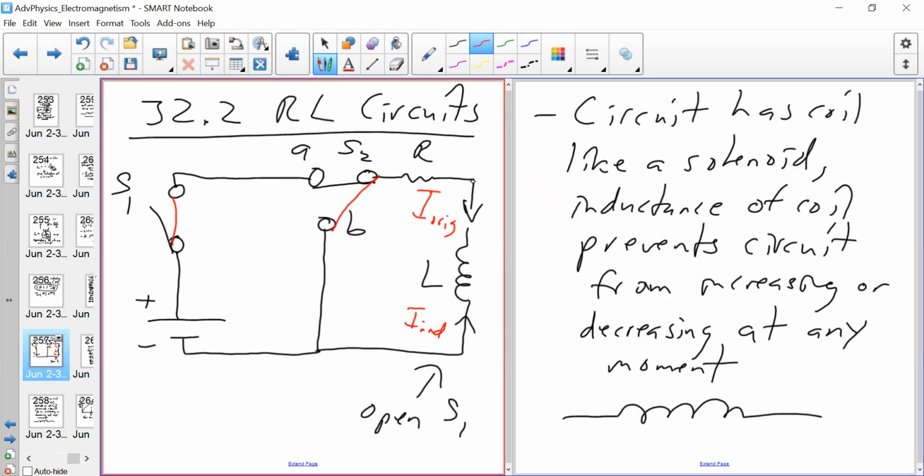So now I hope that we have full appreciation for the circuit diagram. In the first case, the current is going to increase gradually to E over R. At some point, when the time constant reaches L over R, it reaches 63%, and then we're on our way to the max. It's going to limit as t goes to infinity. It's never going to reach the max because of this inductor.